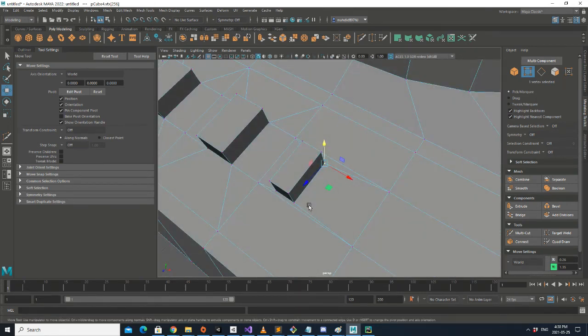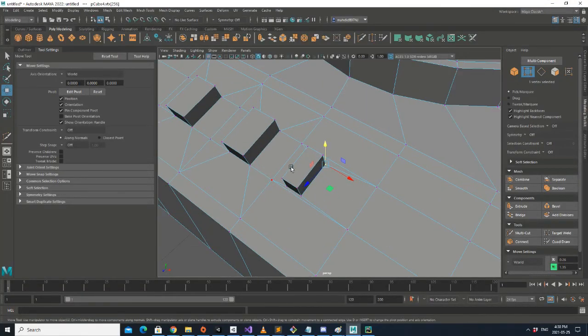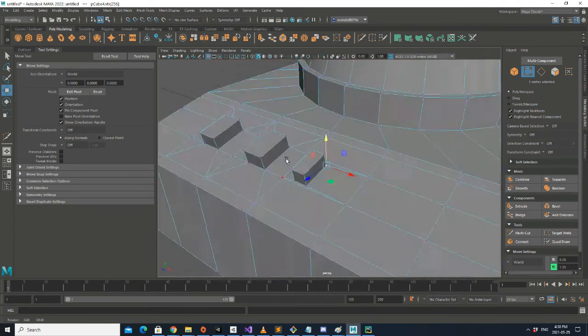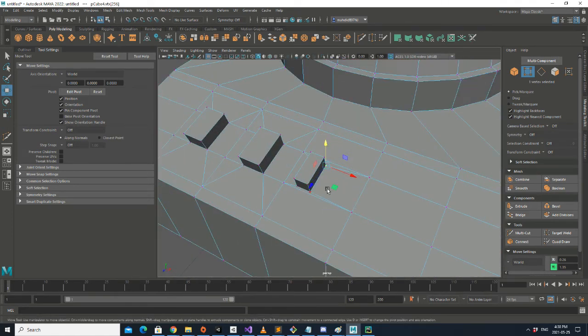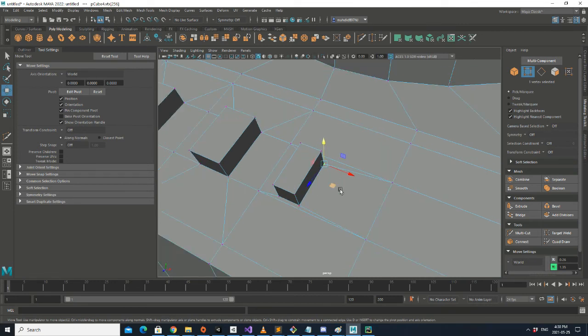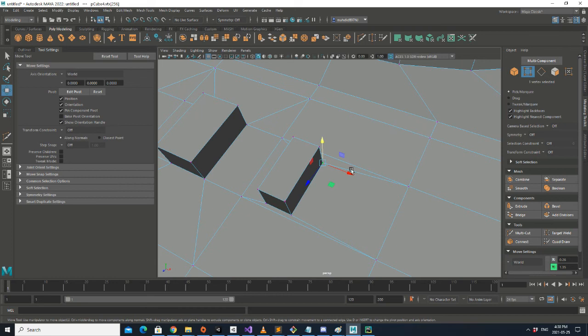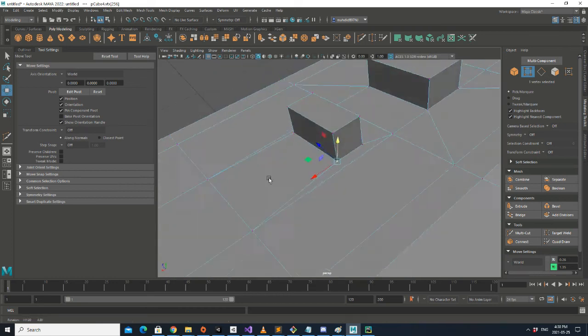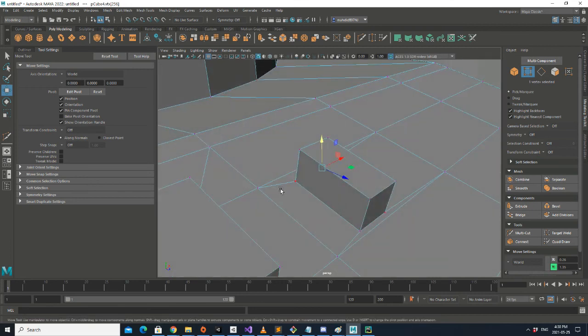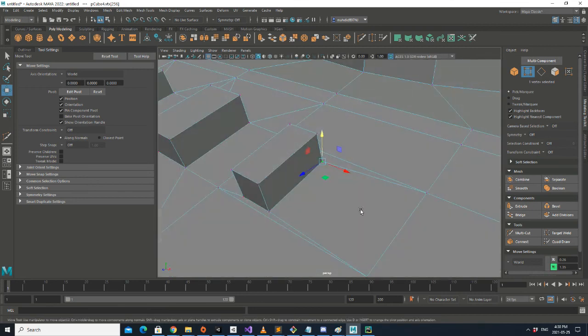So actually these are the two best ways that come to my mind for adding buttons. I think the second one is easier. It's just adding your cubes, making the union between the objects, and then managing your faces to have faces with 4 vertices.